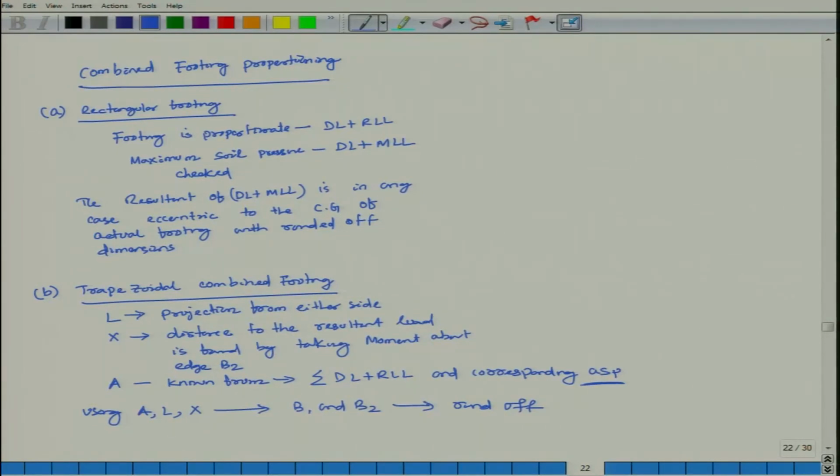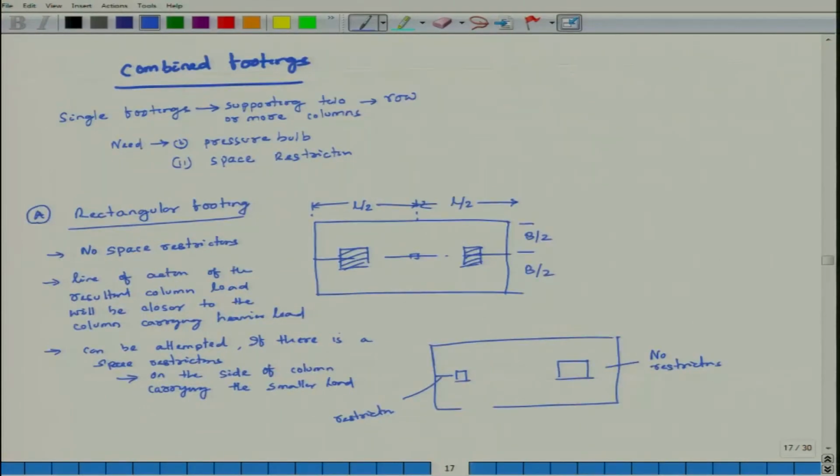Also, as width is varying, soil pressure P is equal to V by A plus minus My by I. I is your moment of inertia about the centroid axis, M is your moment. So, this has to be calculated, this is about your proportioning. All what I have discussed now, I will solve a problem, probably in the next class, as it will take long time.